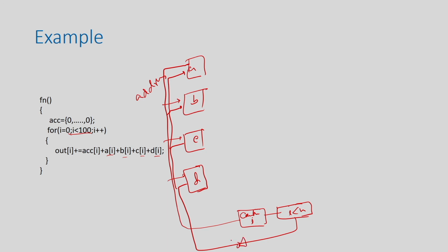So, I will say that this is a read, you just read from this data, and then I will get this A[I], B[I], C[I] and D[I] here, right. So, this is how I should access this. I am assuming these arrays are mapped to block RAM. Okay. So, now I have all this data, and it will need one cycle, right, because these are all 4 parallel RAMs. So, this will need one cycle, right, and then I want to schedule this.